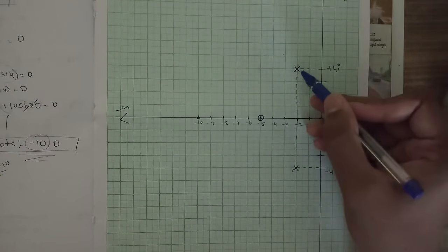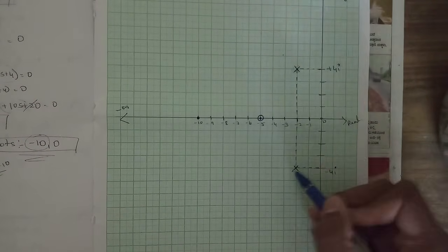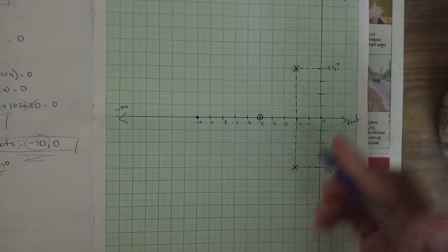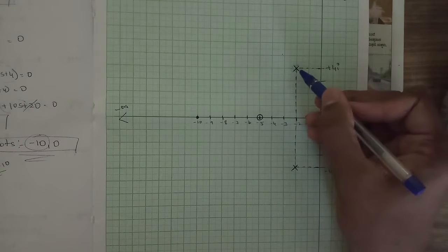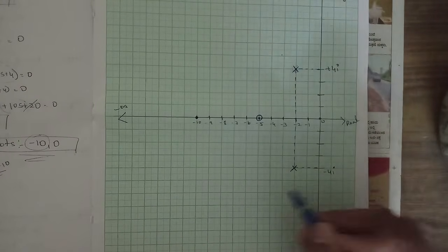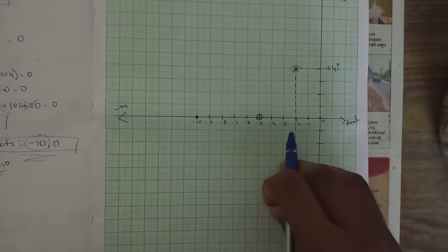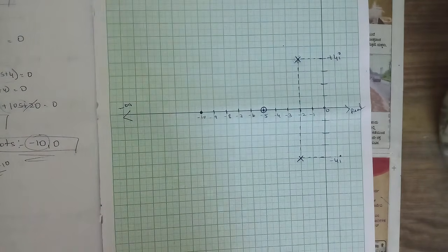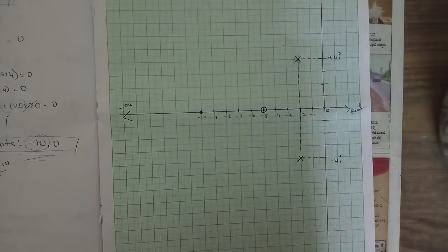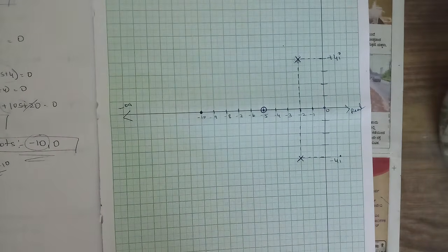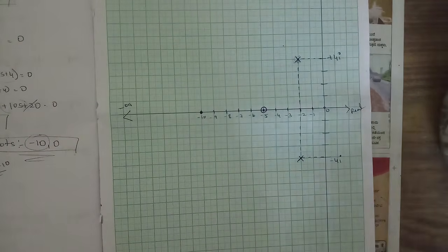But in this case, since the poles here are in the same line, if we get any one angle of departure here, the opposite of this angle, or the mirror image of this angle, we need to be drawing here. So in this case we need to be finding only one single angle of departure. Okay, so let's see how to find that angle of departure now using the graph only.